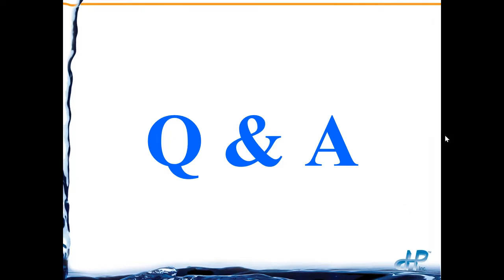Okay, that one is just a partial question. It just says not for wastewater, question mark. I guess I would need to know at what point in the presentation that was chosen for. If you're referring to is contacting style ideal for wastewater, you can use it in wastewater, but make sure you use a 4 electrode and probably one of the higher cell constants, the 1.0 or the 10.0, because of the range in which your wastewater is going to be.